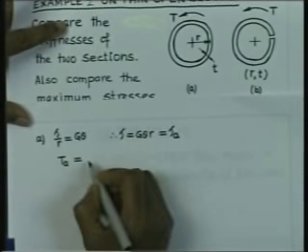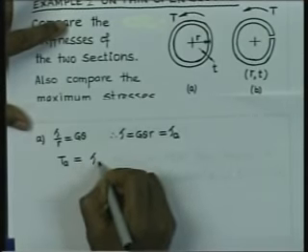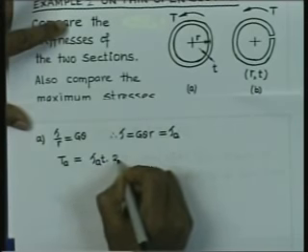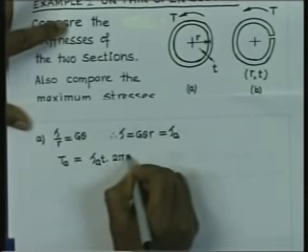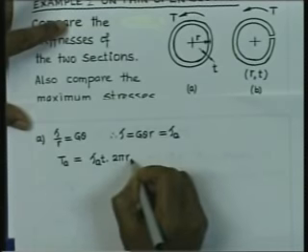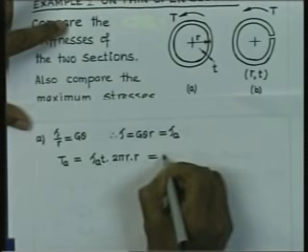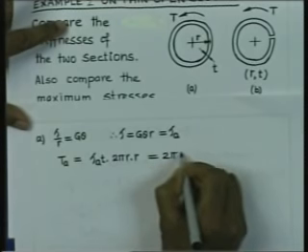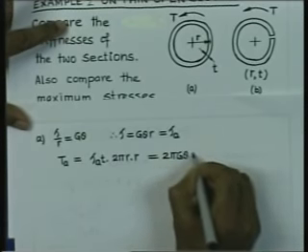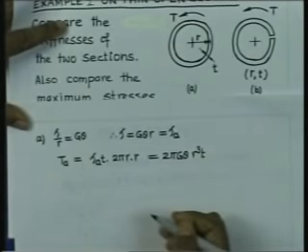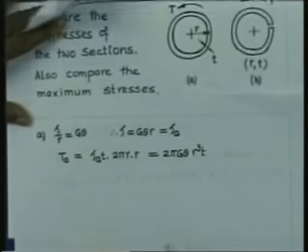The shear flow multiplied by the total circumferential length gives us the total shear force, acting at a distance of r. So, that is the total moment, 2 pi G theta r cube into t. That is the torque in case number 1.